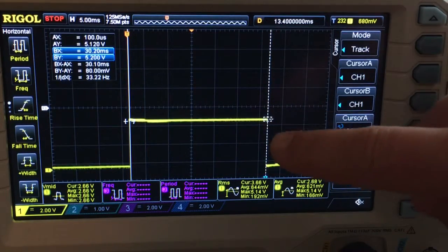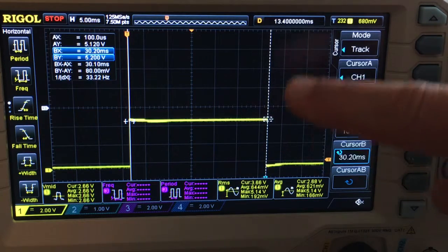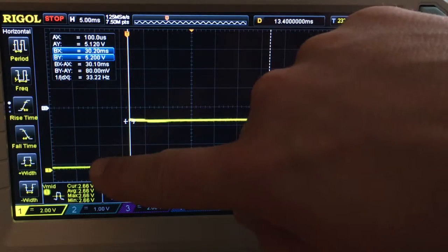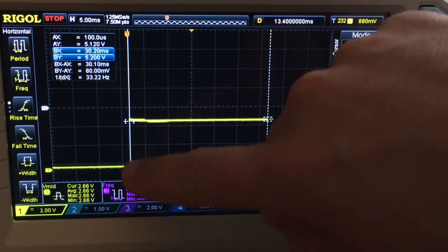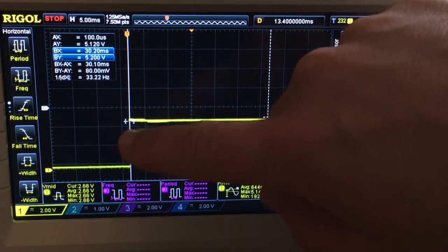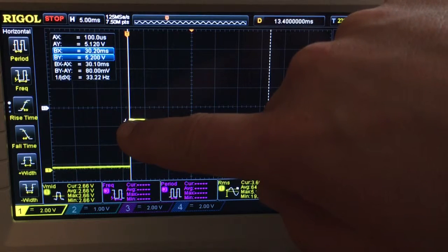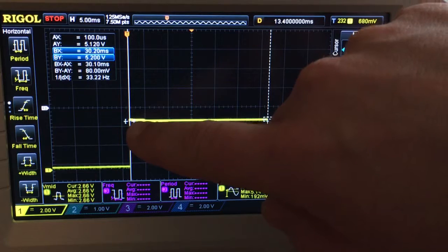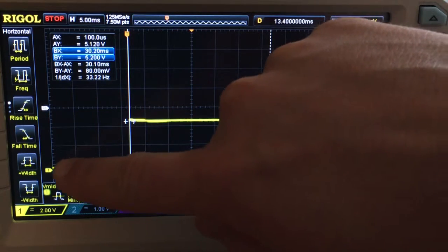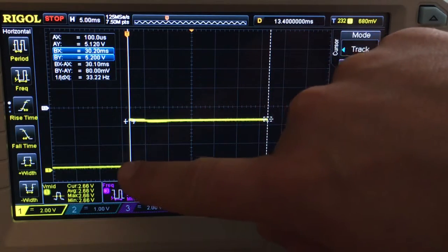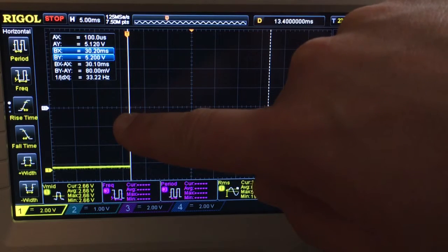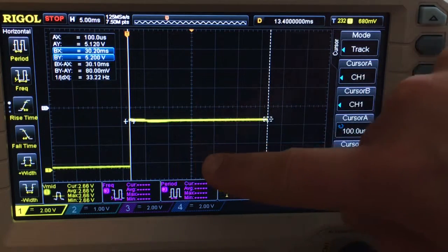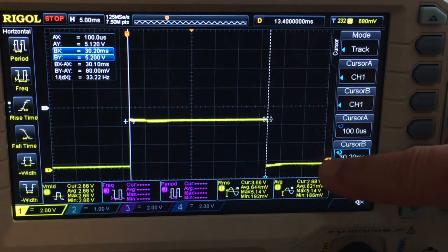Now, if I had a camera set up to take a picture, set to a strobe mode, what would happen is, as soon as this signal rose, what's called a rising signal, the camera would begin its exposure operation. Let's say my exposure was 10 milliseconds. So here's nothing. The camera begins this exposure. 10 milliseconds occurs. The camera stops its exposure and then waits and continues waiting.